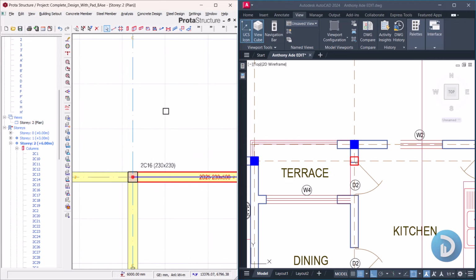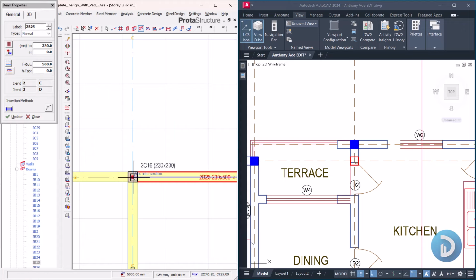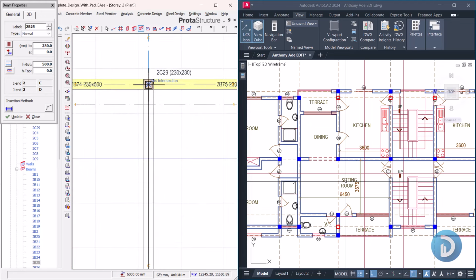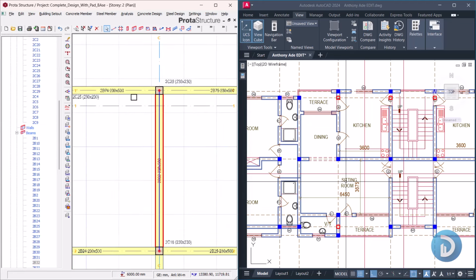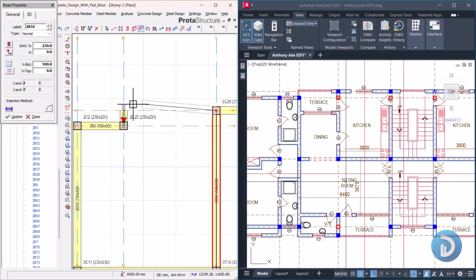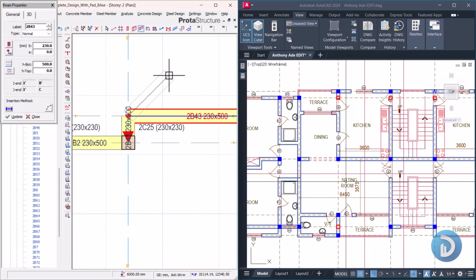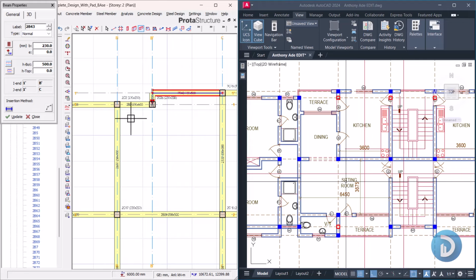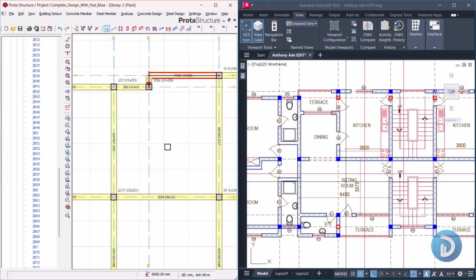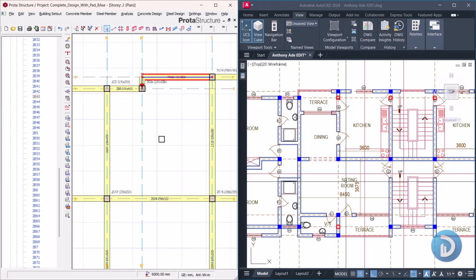click on beam. We can run a straight beam from this column, which is this, up to this newly introduced column. Okay, so we'll do same thing here. For clarity's sake, let's delete this beam and we redraw and cantilever to this extended column, this extended beam rather. So now we have our slab panel in this manner, okay, for this very floor.